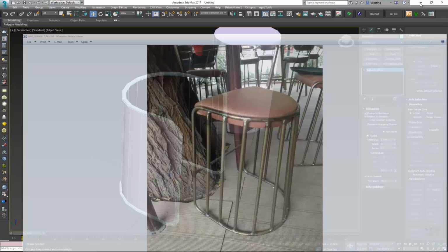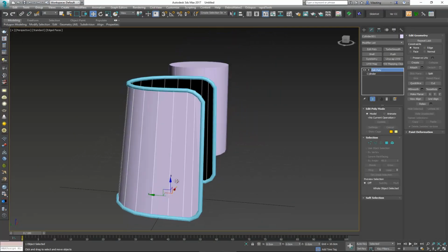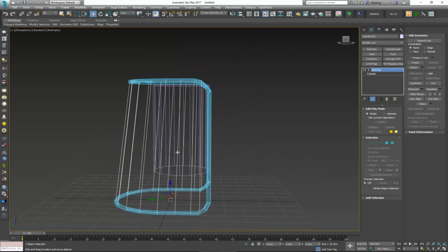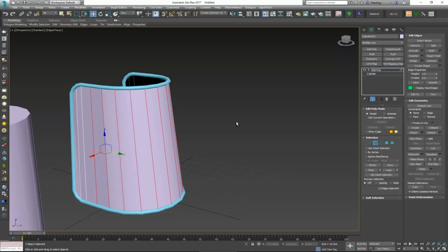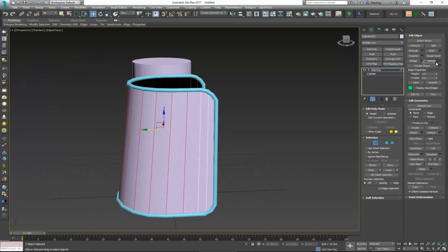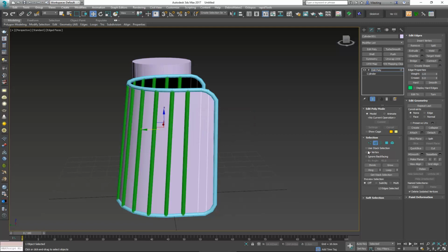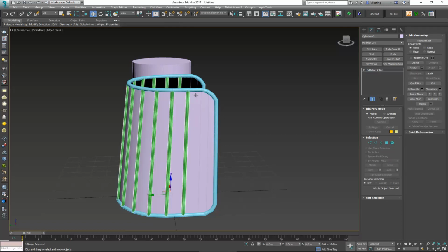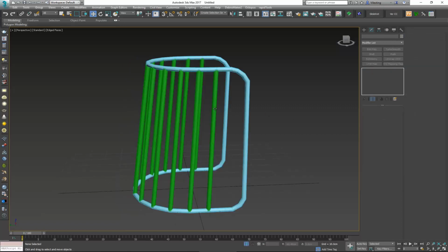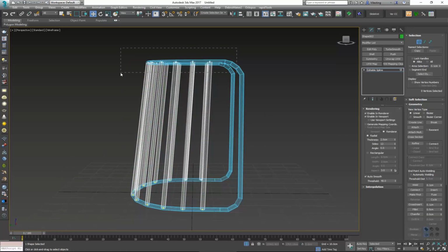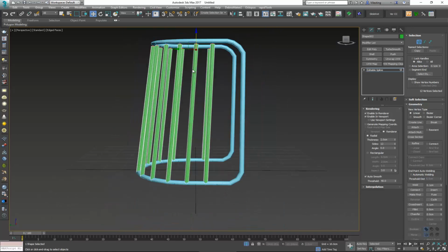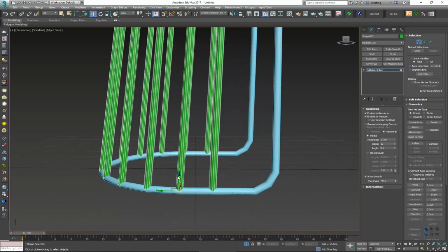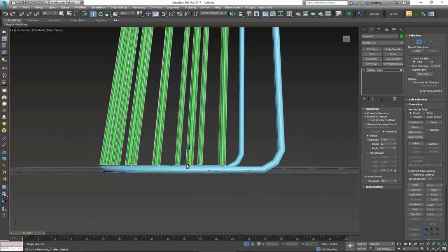The easiest way to do it would be to go in here, and now with this geometry present, just select all of these edges that we want to have a bar on them, and just easily, as we did it previously, create a shape out of it, make it linear again, and just select both, isolate them, and now select the top vertices and move them down ever so slightly like this. Select the bottom ones and move them up ever so slightly like this.